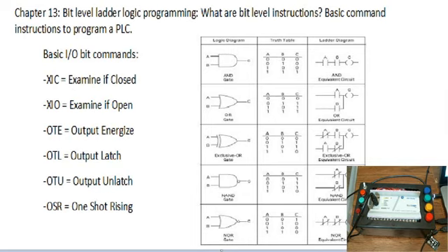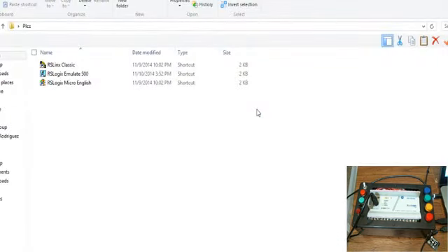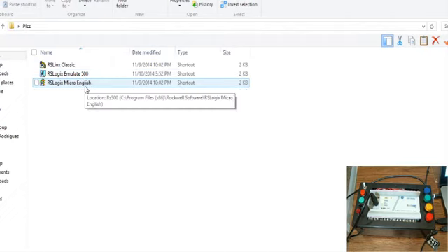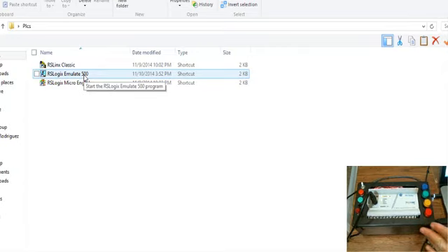I have the software here somewhere, and by this time you should be familiar with the two options of software we're using. One is RSLinx Classic with RSLogix, with this piece of equipment, the hardware. The other one does not use the hardware, but adds RSLogix Emulate to the two previous software pieces. If you try to use them both at the same time, you're going to have a conflict, so they don't work together. One or the other has to be used. In this particular instance, I want to use my hardware here.